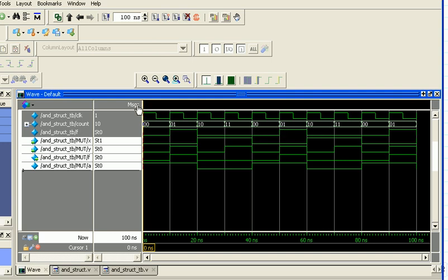Every 5 nanoseconds, down here is the scale of the nanoseconds. Every 5 nanoseconds, it changes the value from 1 to 0, from 0 to 1, from 1 to 0. So it makes a total period of 10 nanoseconds for each clock cycle. And my outputs now are going to be changed in that rhythm of the 10 nanosecond periods.